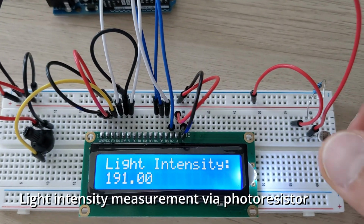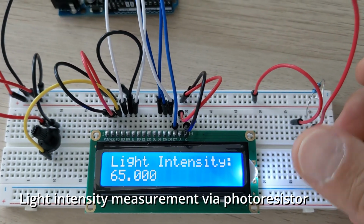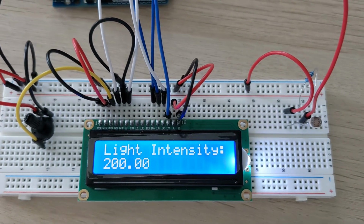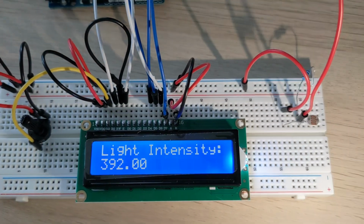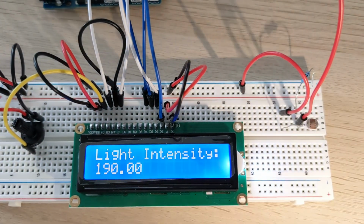A photoresistor is a light-sensitive component whose resistance decreases when light hits upon its surface. If we place a wire connected from one of Arduino's analog inputs between the photoresistor and another fixed-value resistor, we are able to detect the resulting voltage drop caused by the component's variable resistance.